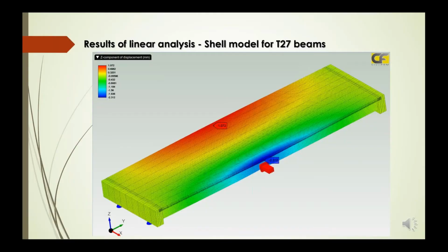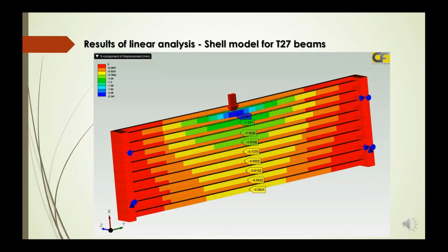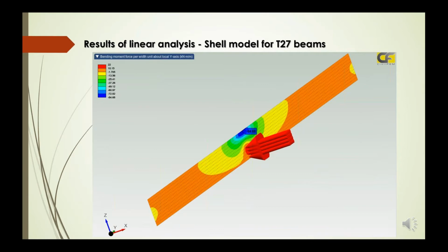And well, some results we have of this model. Here is the displacement due to the impact in millimeters. We can see the impact creates a little bit more than 2 millimeters displacement. Here we can see from the bottom view how all beams are affected. So you can see this is a precast T-beam bridge with a compression slab on top, and just plotting bending moments on the impacted beam, just in the web part.